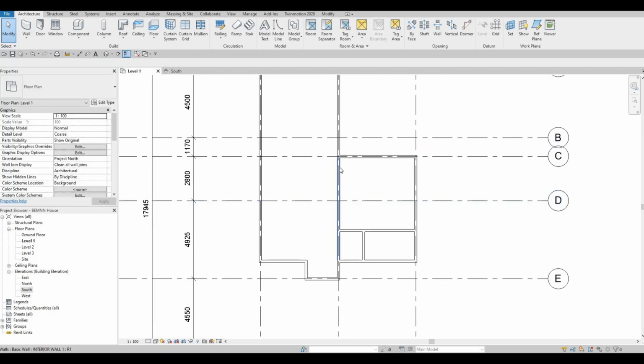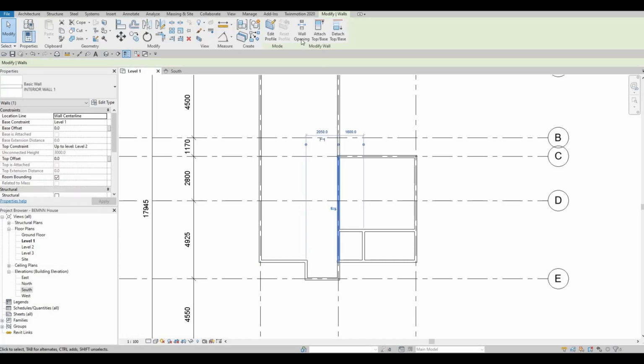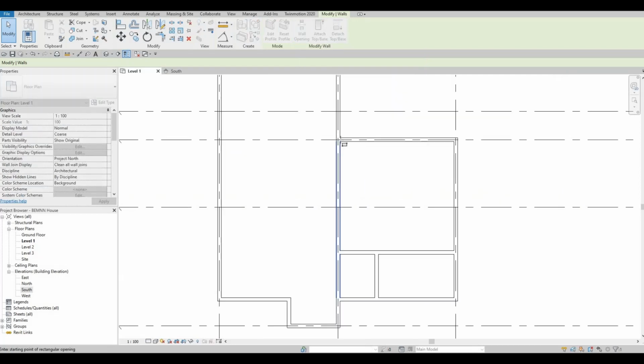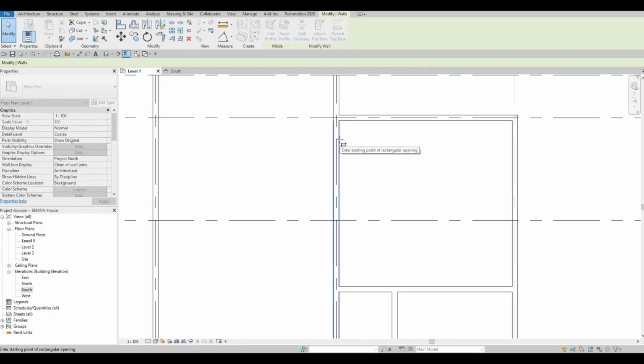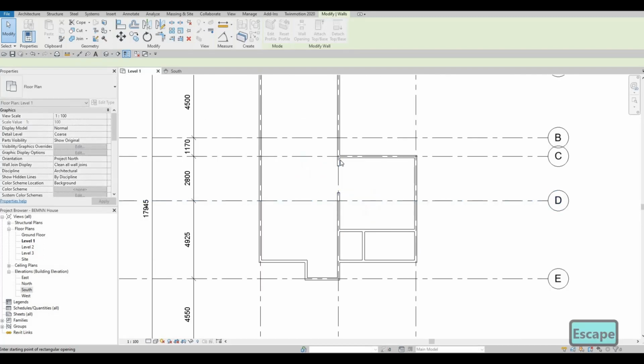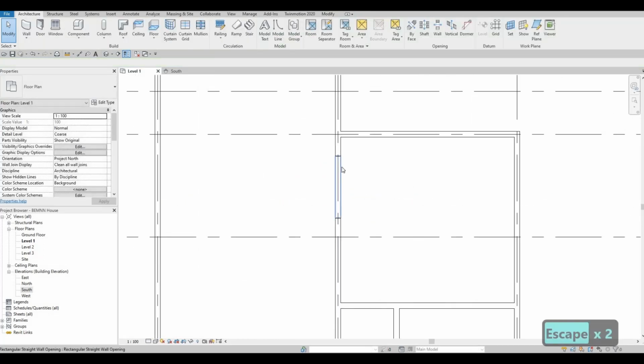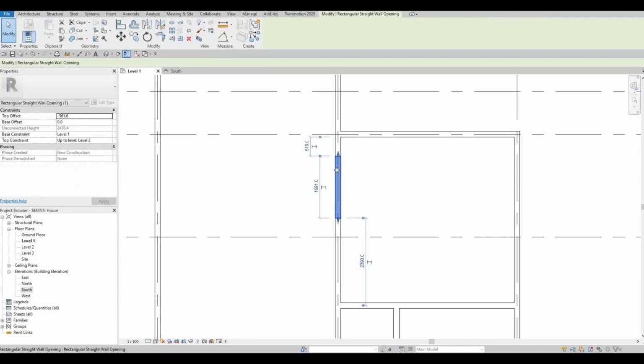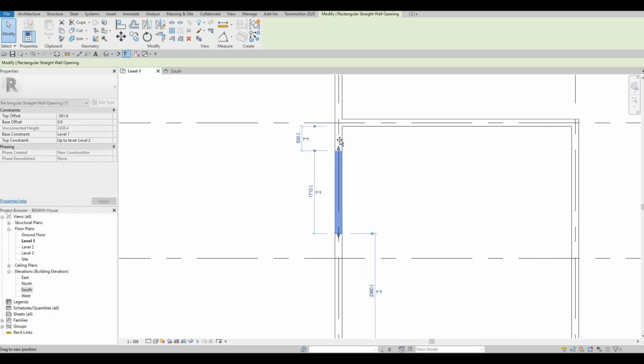And then here, what we could do is select this. Once you select that, we're gonna create a wall opening. Select this wall opening, and then here, select the wall, when it will start and when it will close. So now, as you can see, once you hover your mouse crosshair here, you can select that, and then you can grab it and extend whatever you want.